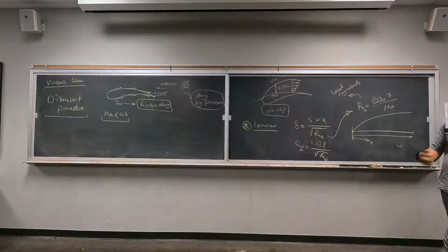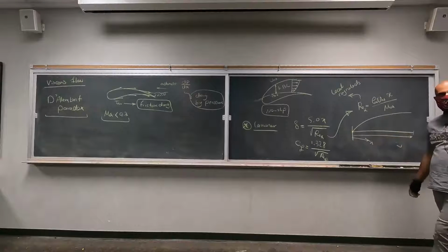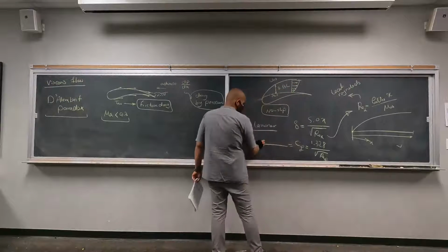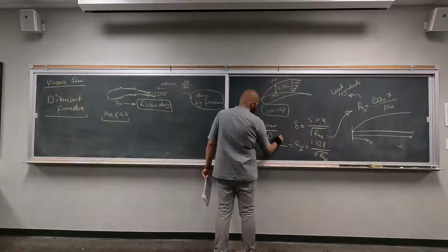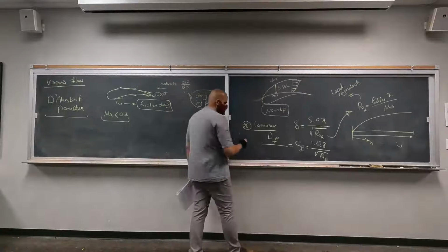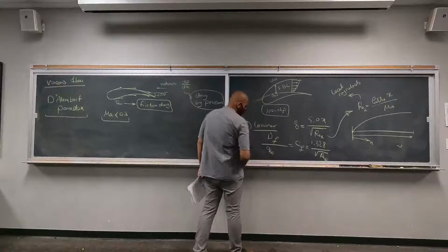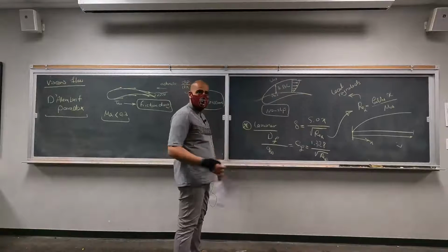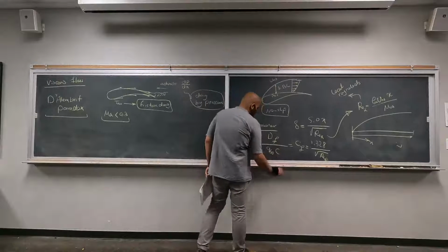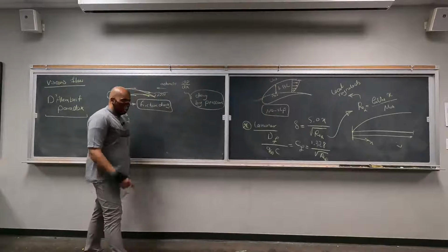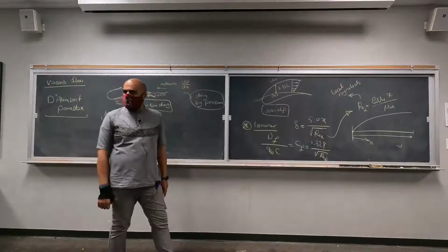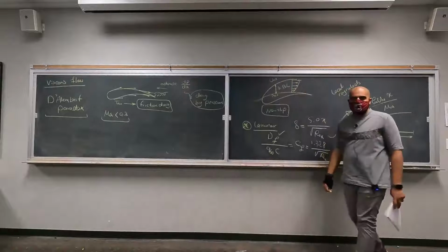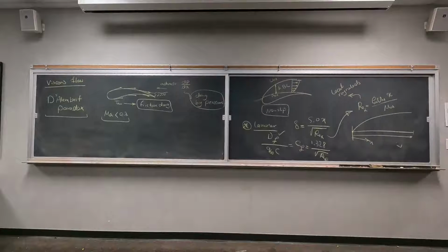Your force coefficient, in this case the friction coefficient, is equal to that specific force, which here is the friction drag, divided by q infinity multiplied by your area, but we are dealing with a two-dimensional case, so that's only the chord length, right? We have q infinity, 1/2 rho v infinity squared. We have the c, we can find the friction drag. Okay?